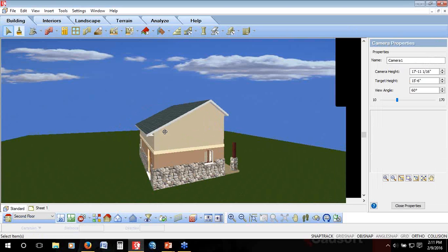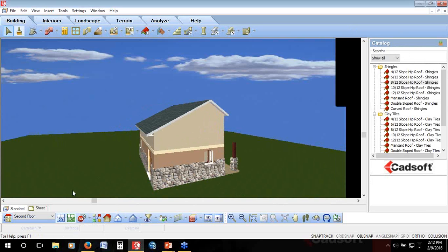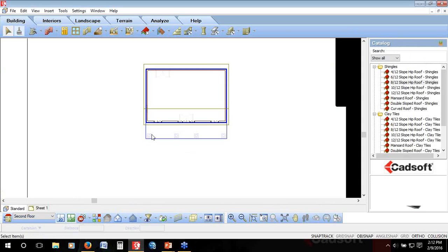So first determine how you're going to put on the roof, roof by perimeter, roof by picking points. Find your gables, and then after you're done your gables, that's when you're going to start changing sides of pitch and plate height and modify all the different arrows. Take a look at the roof, what needs to be changed, find the arrow that needs to be changed, and select it and change it. Okay. I'm going to put this back into 2D. I'm going to slip us down now to the ground floor location.